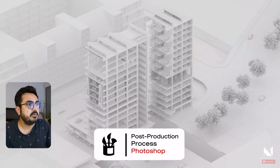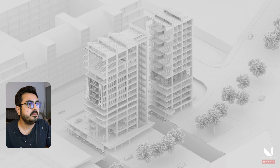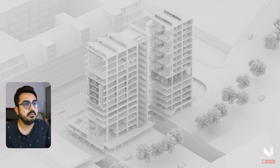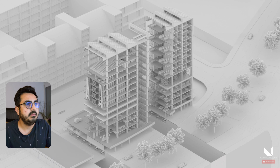Moving on to the next step, which involves Photoshop and post-production of your work within this program. The first step for this is to import all the saved render elements from 3D Studio Max and V-Ray. So you can tweak the contrast of your work in comparison to the output you've obtained, camera settings and lighting, slightly enhancing the contrast as needed. Here I've increased the contrast a bit. In the next step, I selected the floors and assigned them a light gray color using the render element, VrayWireColor, which boosts the contrast a bit. I also enhanced the lightness slightly.